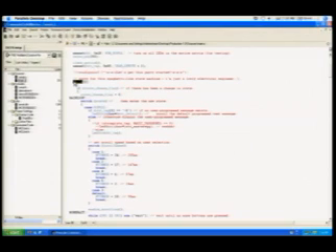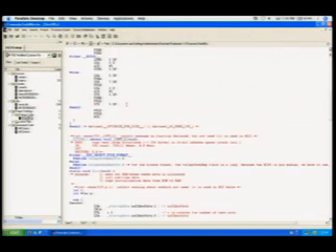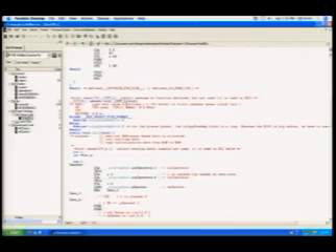Thank you. Anyway, you'll notice that it says while 1. So basically, this will execute this loop of code forever. After it starts up, it runs initialization code somewhere in here, which is, as you see, assembly code. It initializes various registers on this chip and gets it configured for working with these shifters on the back and the optional accelerometer and Zigbee chip, so that the chip knows how to talk to its peripherals. That all happens before you hit the main loop.